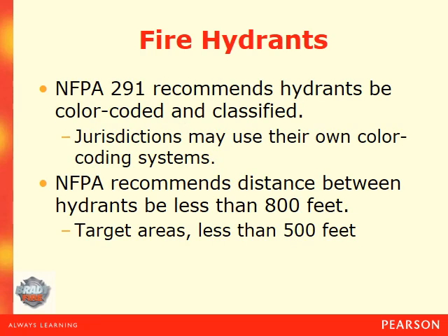NFPA 291 recommends hydrants be color coded and classified. Jurisdictions may use their own color coding system. NFPA recommends the distance between hydrants be less than 800 feet, with target areas, meaning special hazards, at less than 500 feet.